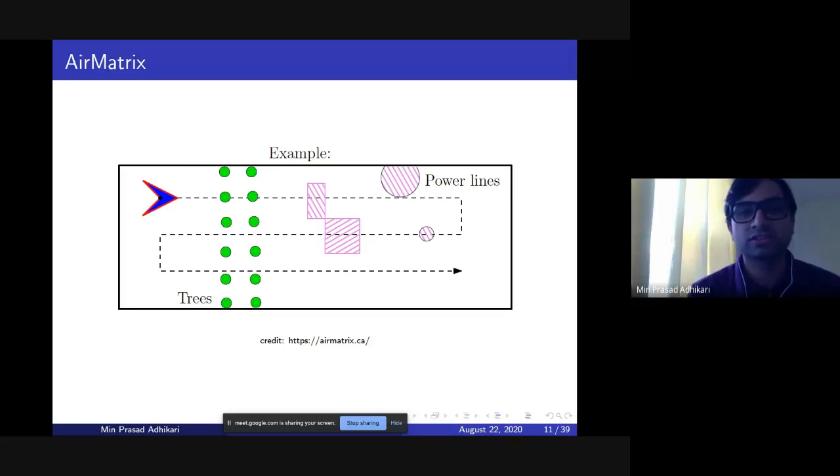When you see the obstacle, you're flying at the minimum velocity, let's say 10 meters per second or something like that, and at that speed you want to be avoiding obstacles, right? So you need a trajectory generation system which is real quick, and you want good computation capability. Though there are really good computers these days, having an algorithm that guarantees at least a sub-optimal solution, or at least a feasible solution within a given amount of time, is really important.